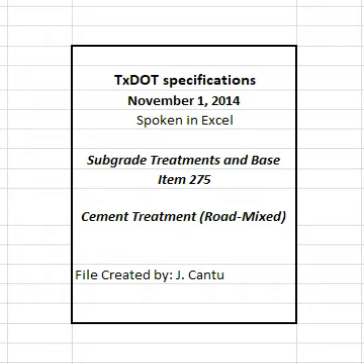4.5.1 Ordinary compaction. Roll with approved compaction equipment, as directed. Correct irregularities, depressions, and weak spots immediately by scarifying the areas affected, adding or removing treated material as required, reshaping, and recompacting.